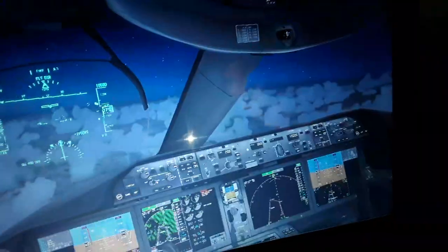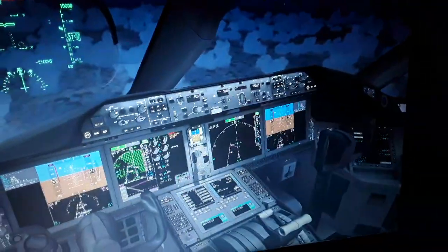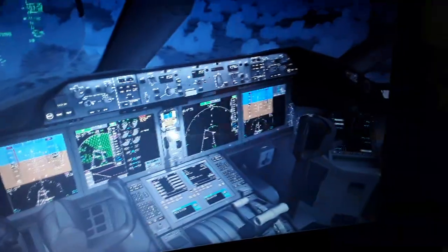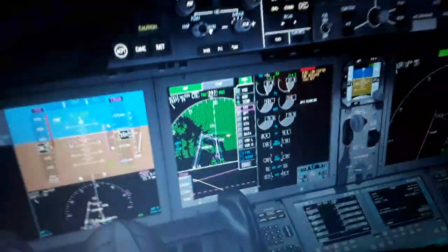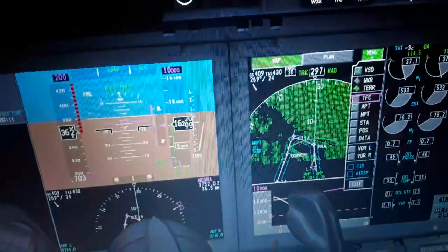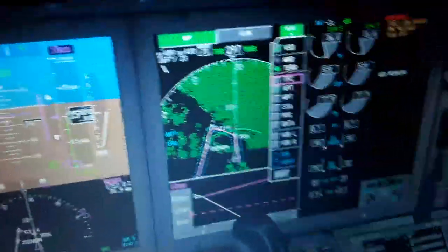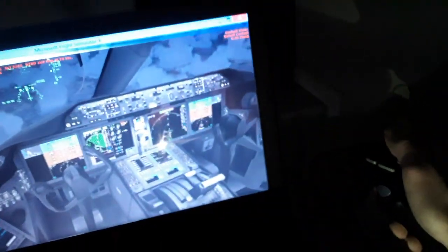So you can see the point of intercept here as we're descending. It shows us we're gonna be leveling off with the autopilot setting right now. Over here you can see the autopilot settings of the Boeing 787 right now for approach. So to descend, we have to cross through these waypoints for approach. Over here, 15,000 feet. So we need to start the turn now for approach.